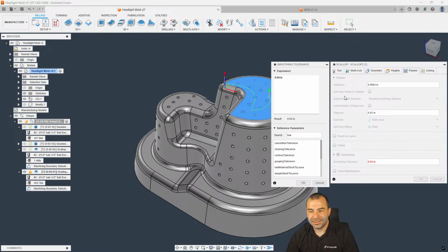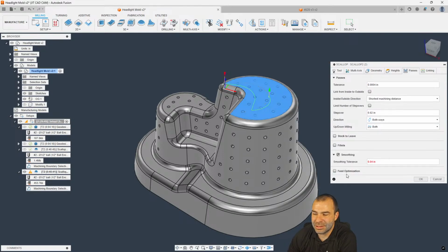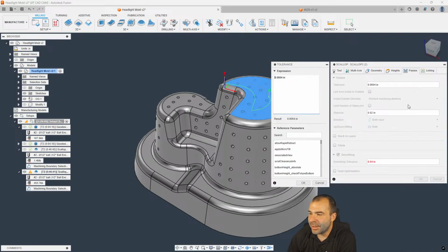So it looks like Matt's putting it in there. Just put plus tolerance. And you could 100% adjust that. Again, it depends on what you're looking to do. Actually, he wants to do stock to leave, right? You want to do your tolerance off stock to leave. So we can go up here and click these three little points. We can go to edit expression.